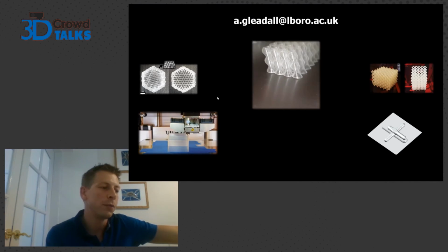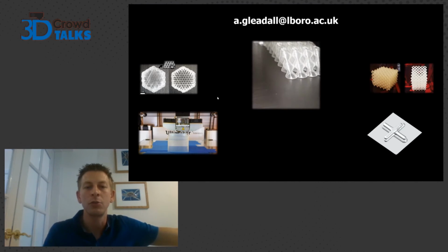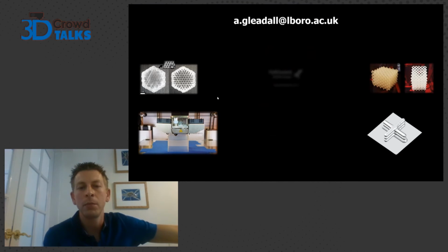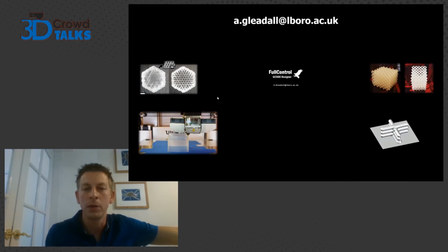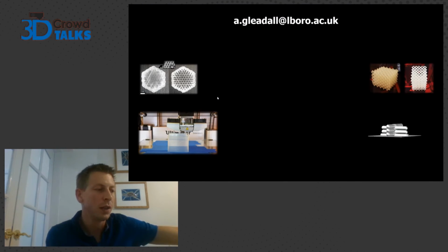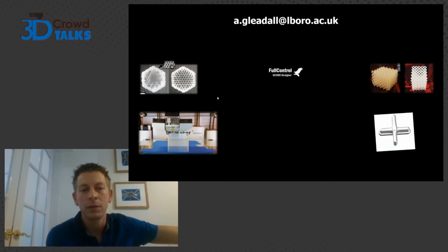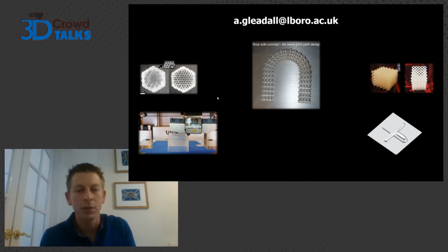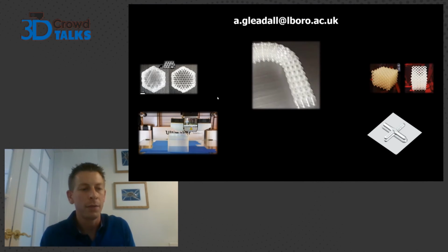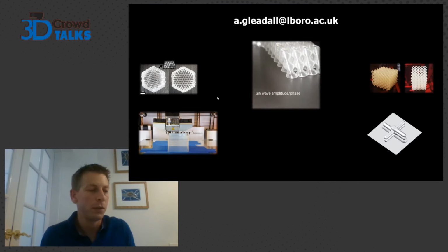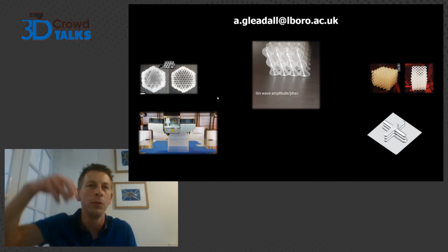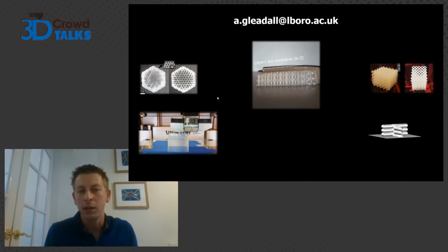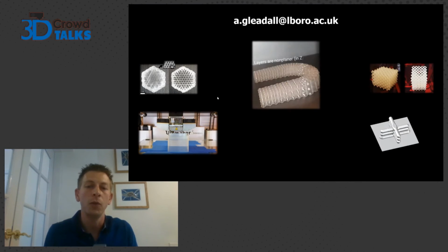And yeah, these have been going for weeks, printing these Zig Zag structures with no noticeable problems. I might not notice the problems because there are so many printers, and printers do break occasionally, but the technician hasn't raised them as causing any issues. I presume there would be an additional risk if your print bed is fairly heavy. It will also depend on the style of the printer and the print area. In some, the nozzle will move up and down, and in some, the print bed will move up and down. So it would need to be investigated specifically for that printer.